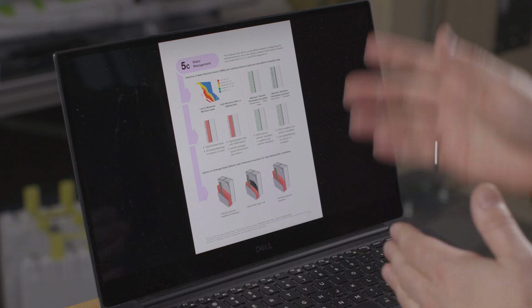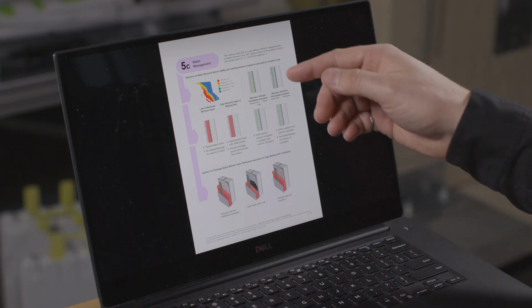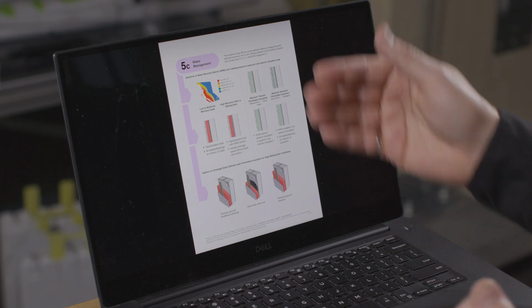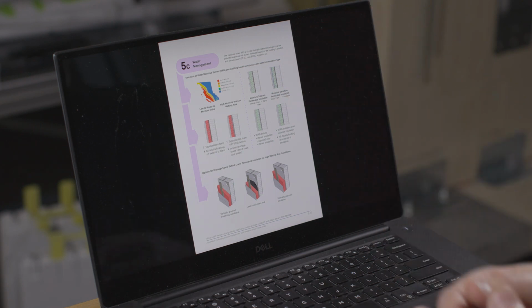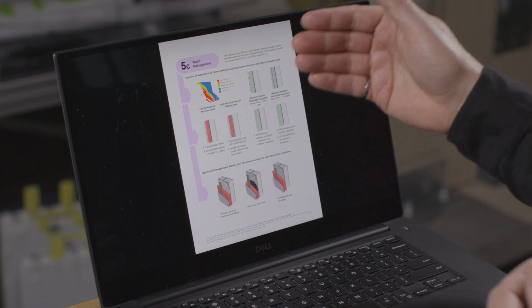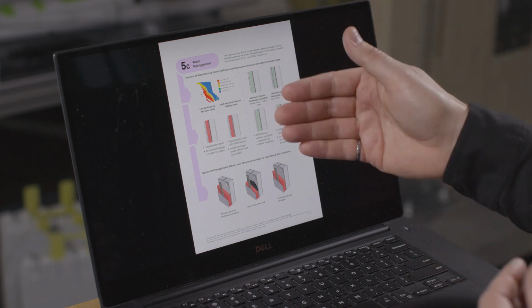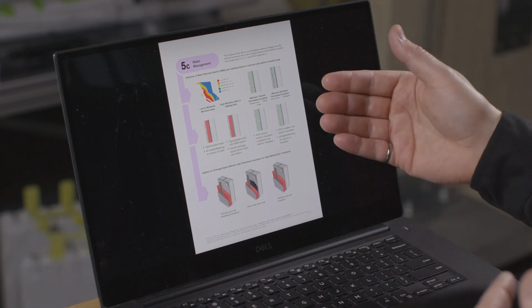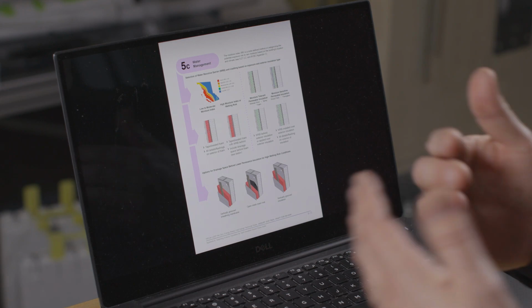Then on the right-hand side, we have vapor permeable insulation. And so you have moisture tolerant insulation versus moisture sensitive. The key rule of thumb there is if it's moisture tolerant, things like mineral wool, then the water resistant barrier can be inside of it. If it's moisture sensitive, like wood fiber, then you need water control on the outside. And that follows through into the flow chart there.